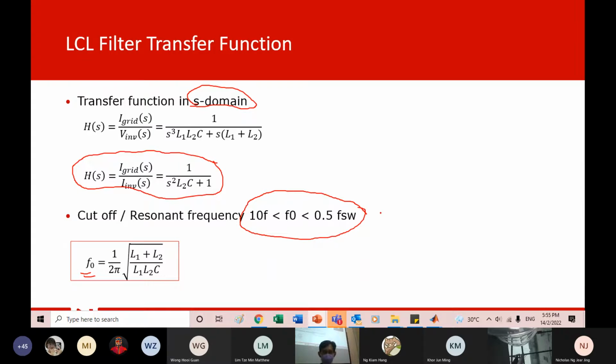Another important thing is that for a grid inverter, the LCL is much more important in the sense that it causes a safety issue. With an LC filter, if you calculate wrongly, never mind, because the load is isolated. The most it does is explode your load. But now you're connected to the grid.